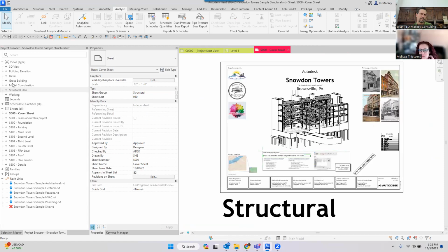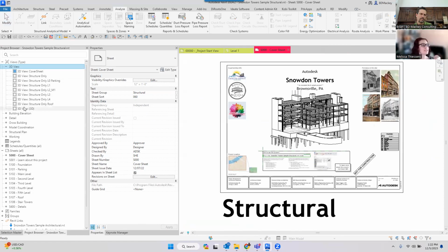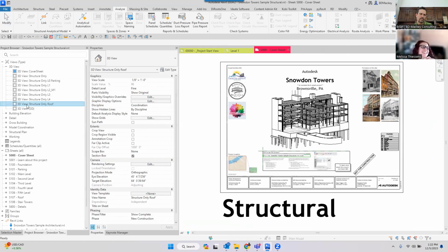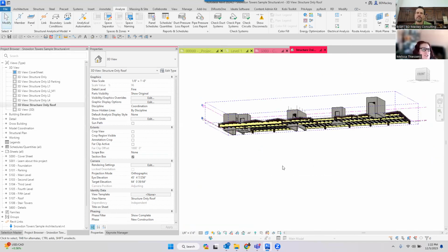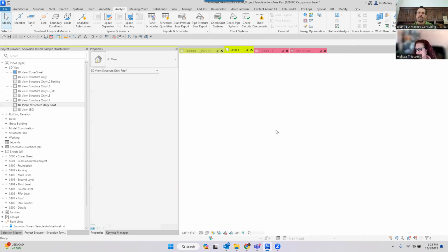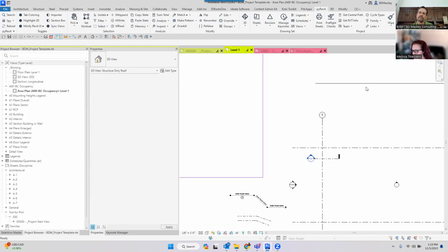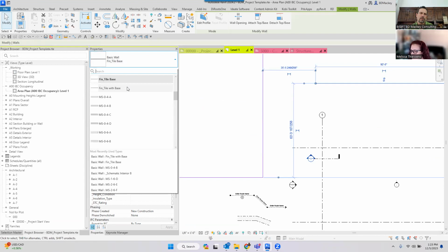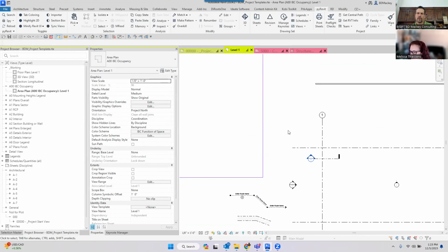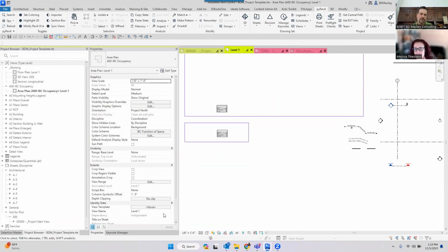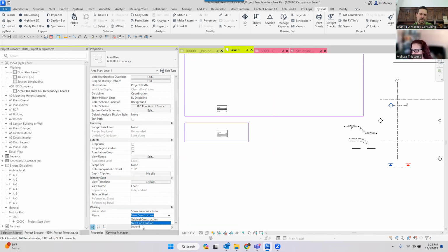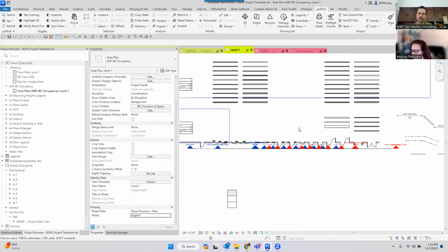Well, since we kind of semi-failed on that one, we'll do Desiree's other question. Can a wall tag show lengths of openings that are inserted into the wall? No, but you could do something else. So if I come back to this little file here, I was trying to set this up. So if I grab this, change this to be a wall that actually has some thickness to it. Cool, there we go. Actually, I don't have to do that. Let me just change my phase in here to be my legend phase, and there'll be a whole bunch of openings in these walls over here.